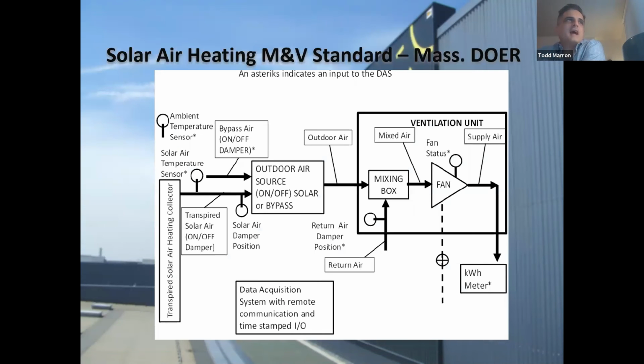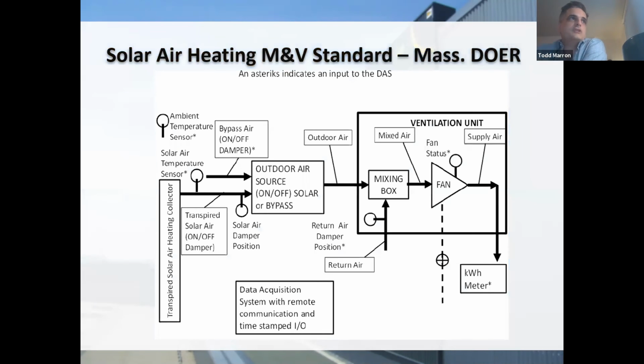And then as kind of a diagrammatic representation of it, one of the challenges that we've experienced is accurate measurement of airflow in the field. So we found that there's been a tremendous amount of sensitivity to the installation, depending on what kind of air measurement device is used. And of course, there's always cost associated with it. So you can spend a lot of money on a very complex air measurement device, but then the danger is it ends up getting value engineered out of the project at some point if it's too expensive.